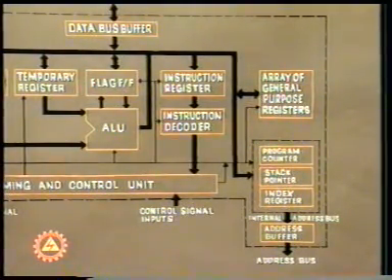The internal address and data bus are suitably buffered to provide the external buffered address and data bus. Microprocessors usually require a single plus 5 volt supply line and a ground line. These are distributed throughout the PCB.